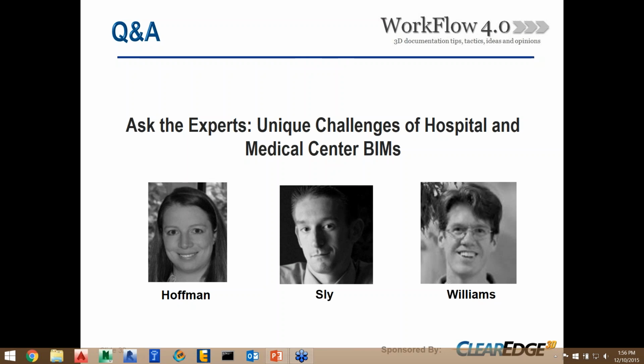When Edgewise does its first registration, it does take a little bit of time, but you can obviously do some other tasks during that. But it's able to extract most of the pipes that you need, maybe not 100%, but you can obviously go through and connect which pieces you need to connect, or extract certain pipes that you need in your model, or even delete ones that you don't. So I think it kind of depends on the project.